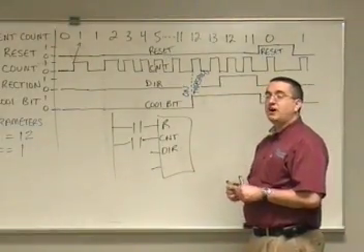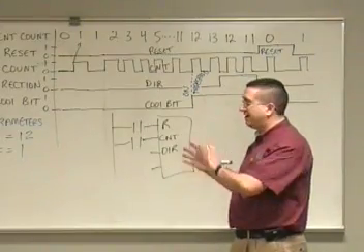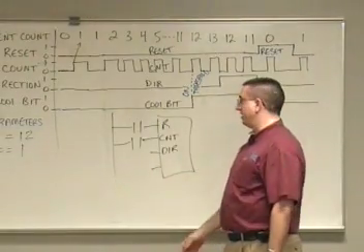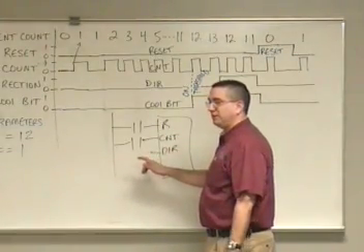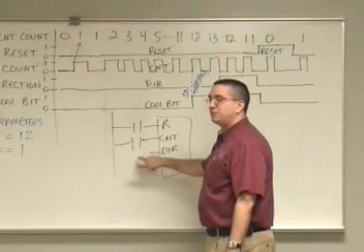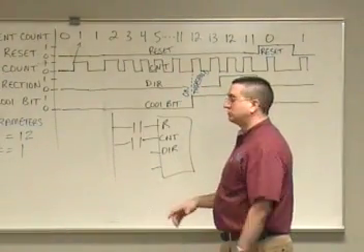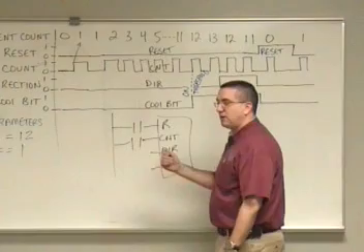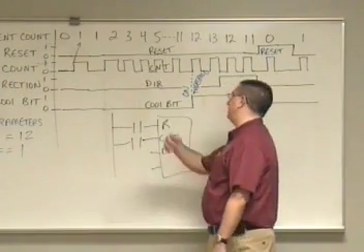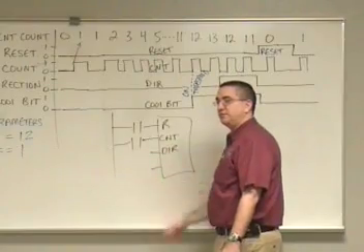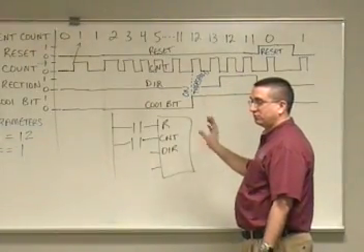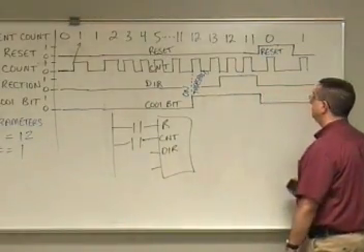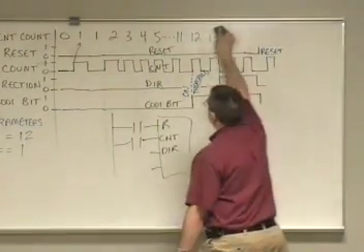On other PLCs, you're going to find out that it's going to say you have to have something hooked up to every pin. Specifically on the S7-224, it would call this a block without connection to an output because something's not connected up there. But LOGO!Soft itself will actually allow you to leave a pin blank. So maybe all I want to be able to do is count up to 12 and then run the packaging machine, then have the packaging machine reset the counter. Any questions on this so far? None. You guys comfortable on it? Pretty good? All right. Let's erase that.